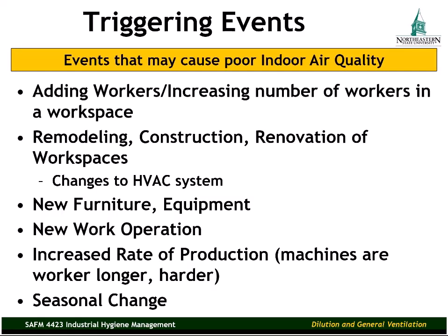And that's one of the biggest problems you see with HVAC systems and general ventilation systems. If they have an air filtering element, it's got to be maintained properly. You got to change the filters. You got to clean the filters. Whatever type of maintenance is required, that's a big part of maintaining the functioning of a system. If you never change the filters, you let the filters get clogged up, that's going to affect how well your system is moving air. And it could also shorten the lifespan, the usable life of that ventilation equipment.